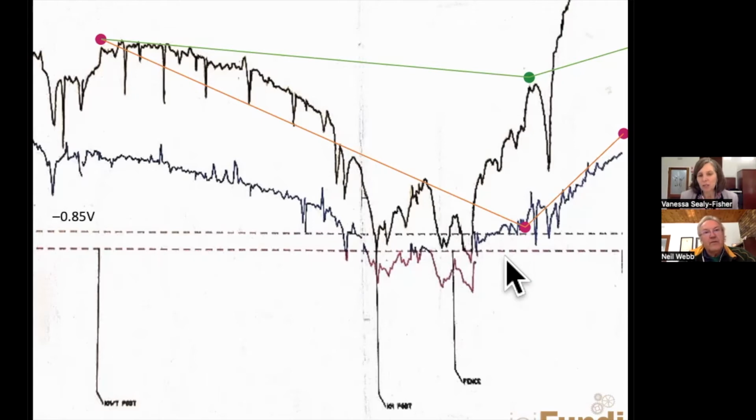There's a concern in my mind that sometimes when you get data like that, where 2 test posts on either side are fine, and one that's not so good in the middle, there's a tendency to write off that as being a spurious data point. And I think this shows that if you do get unexpected data, in this case, poor protection, it is worth investigating a little bit more. It might not be spurious and to be ignored. It may in fact highlight a problem, such as you identified here.